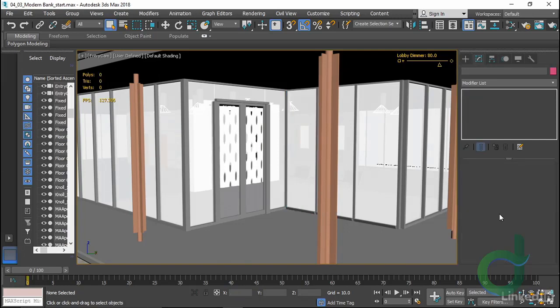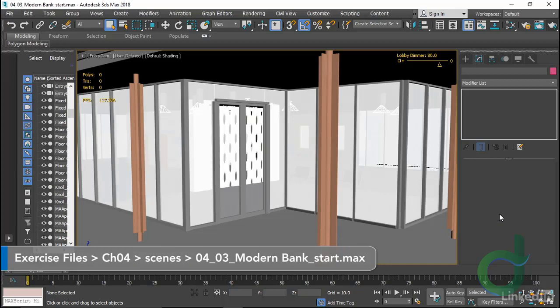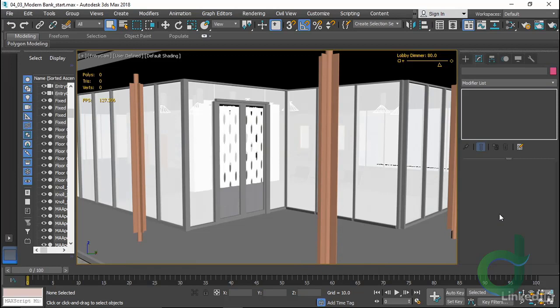The goal of bringing this Revit model into 3ds Max is to fine-tune it for rendering. Now this is not a rendering course, and so we're not really looking at a particular rendering engine here. We're also not looking at this in a true real-time application. We're prepping for real-time, where we drop into a game engine and run around this scene or put on VR headsets. Instead, we're simply looking at the workflow from Revit to 3ds Max and what we need to do to fine-tune and polish these objects. So I'll use a test render in that context, not necessarily making the prettiest image, but testing some things in the rendering to make sure that it'll show up nicely in any given renderer, whether I'm using Arnold, V-Ray, Corona, or the art renderer here.